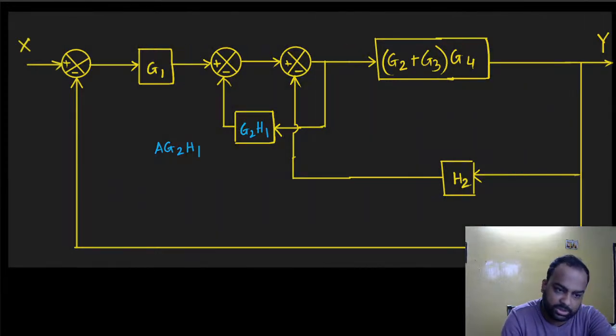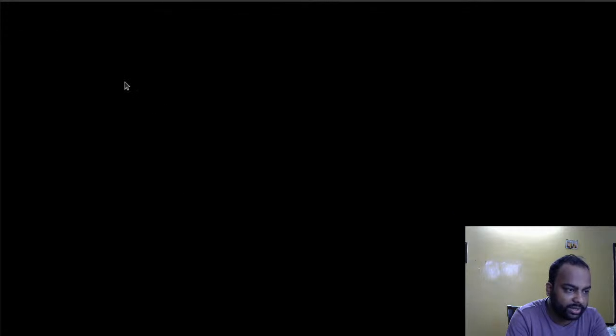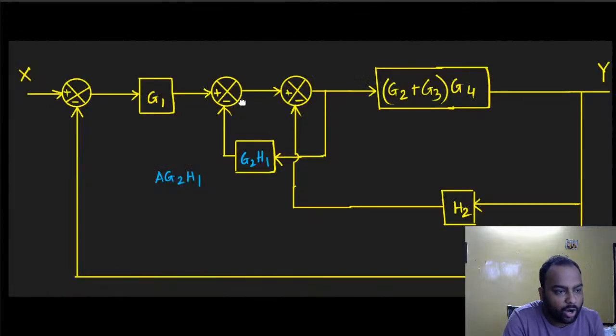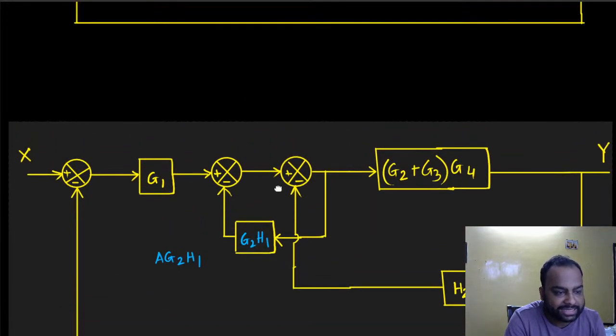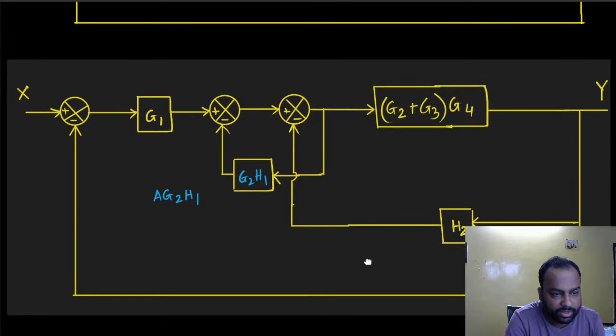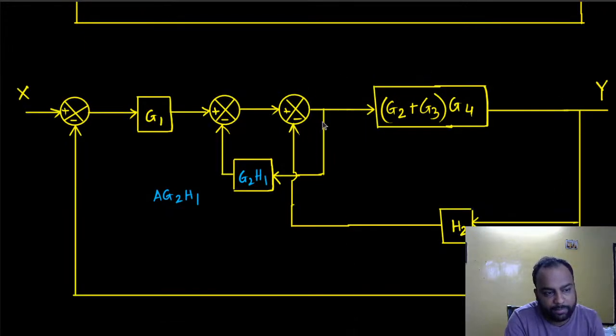This is the only thing you have to remember while doing block diagram reduction. You cannot reduce something that has an internal dependency. I cannot consider this feedback loop and write down a single transfer function for it, because if I construct an equivalent transfer function out of this entire feedback loop, then this point would be lost.